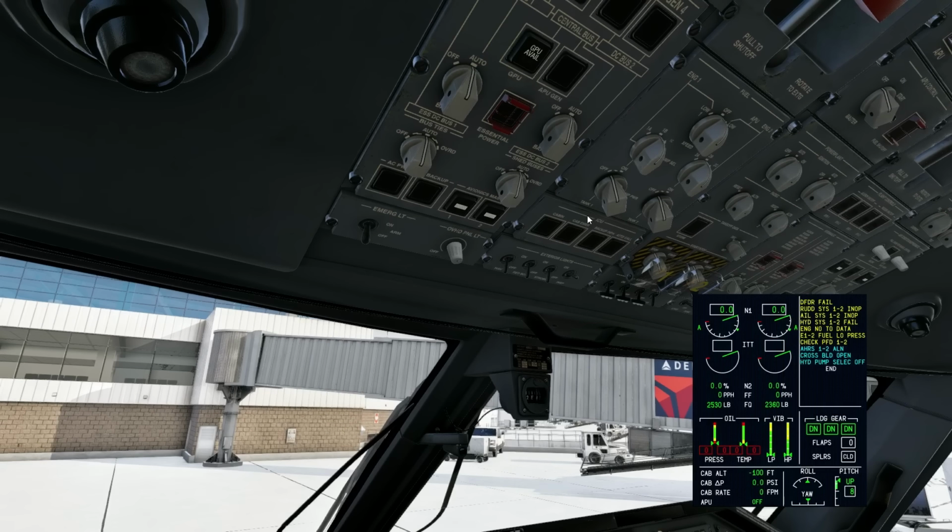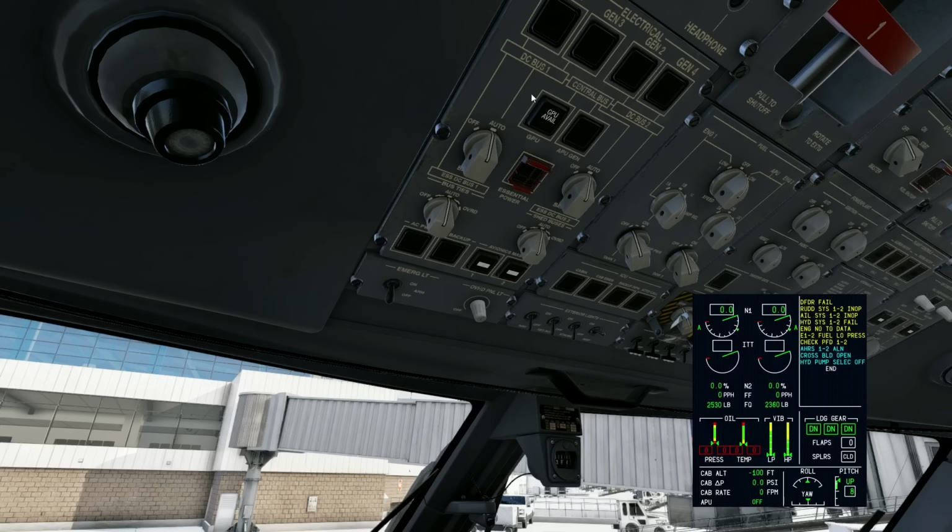And the ground power unit comes alive, or the ground power unit avail light comes on. So this is telling us right now that we have ground power available to the aircraft. Now, here's the fun little gotcha. I don't want to take this ground power until I know it's good ground power. So what I need to do is actually take a look at what the power being put out by the GPU is before I select it.